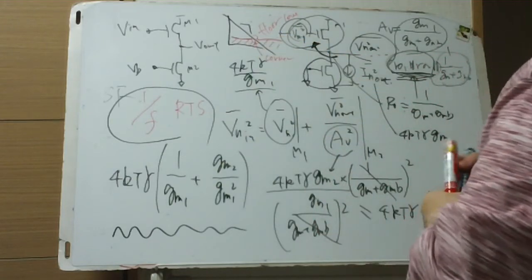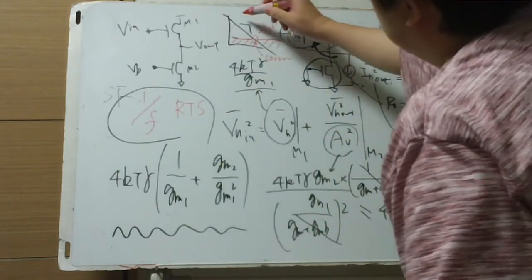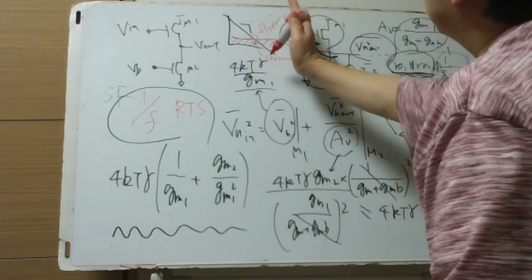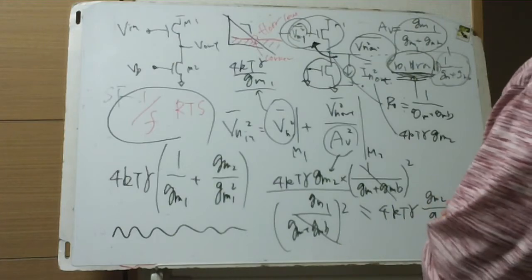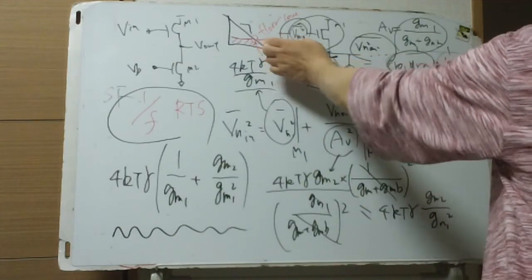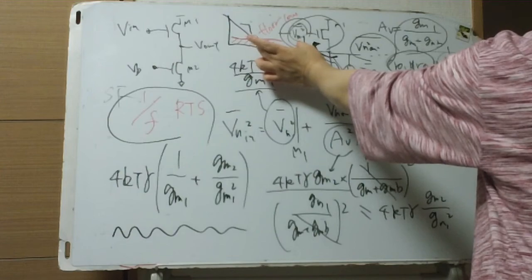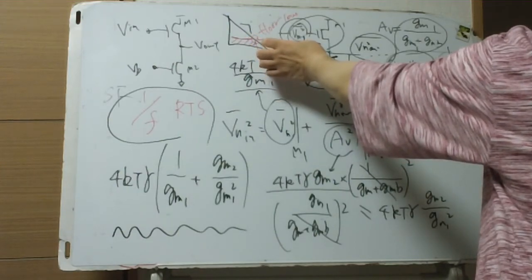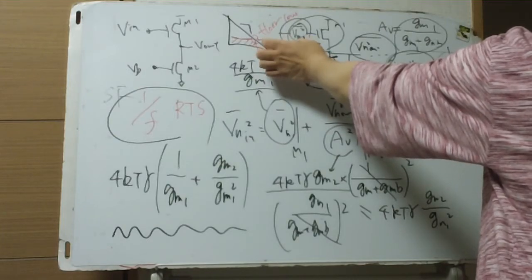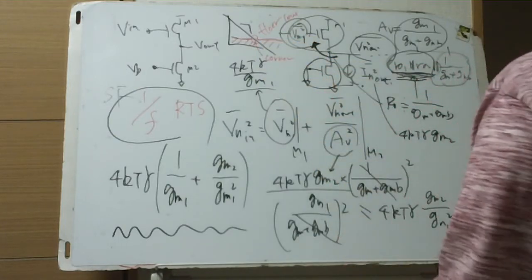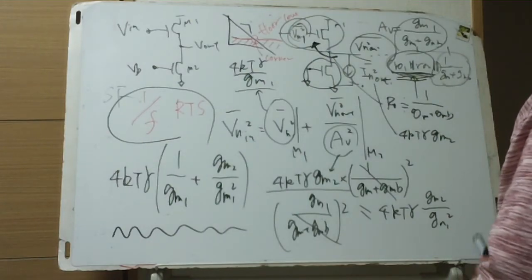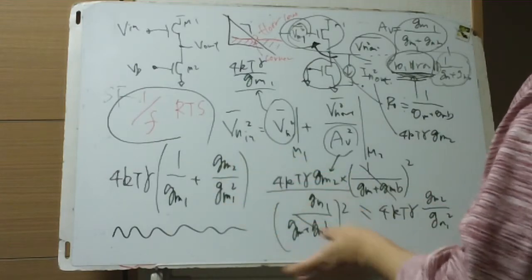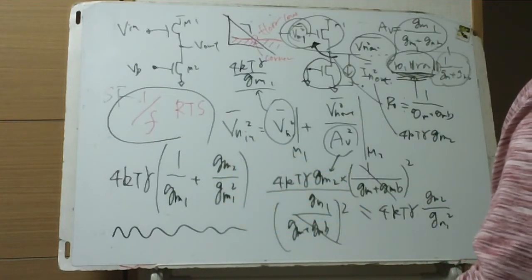Usually an amplifier has a cutoff frequency, noise bandwidth is limited, so delta F is like this area, and we need to sum up the total noise over a very restricted area. A low noise amplifier is realized using these two techniques, CDS or chopper amplifying.